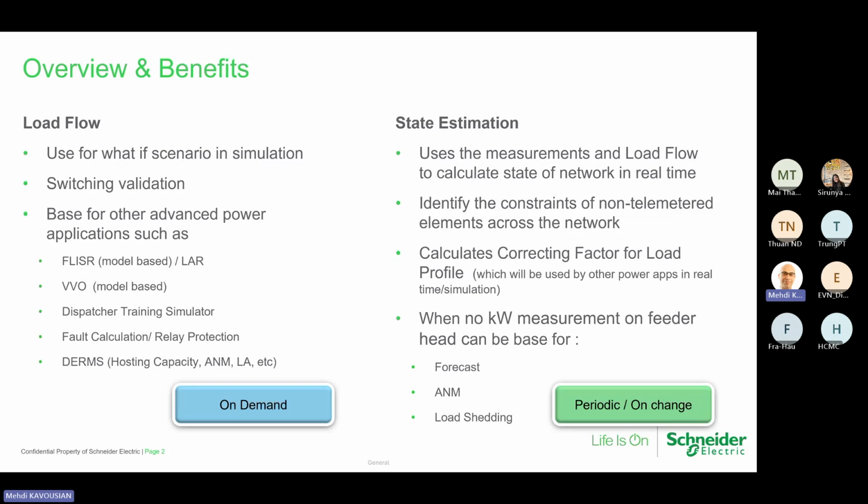The third one is correction factor for loads. The typical load says, for example, now, 1:49 in the afternoon, the load from the typical curve that you have says, let's say, 200 ampere. That's just what load flow says, but your measurement is 240. So it makes the correction. 240 divided by 200 is 20% more, so it will increase the load to match them closely.